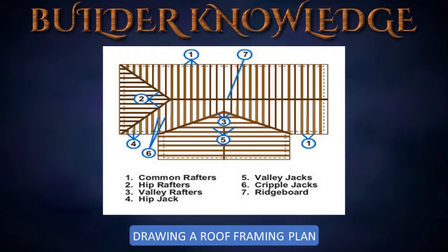Procedures for drawing a roof framing plan. A roof rafter framing plan indicates ridgeboard and rafter size, spacing, roof slope and direction, and all details. It's used to determine sizes and quantities of all components for estimating purposes, and to allow the mass production of all required roof frame components. The estimator may use the same procedures for drawing the roof framing plan to assist in making calculations. This is accomplished by tracing each component type with a different colored highlighter or marker as they tabulate required numbers and dimensions for each component.